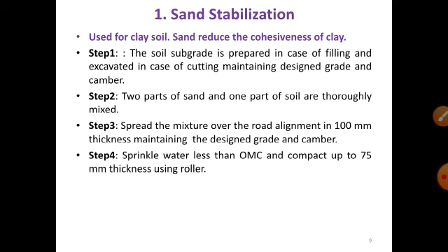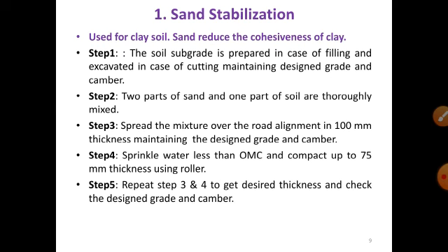So we have to take water less than OMC. Step 5. Repeat step 3 and step 4 to get desired thickness and check the design grade and camber.